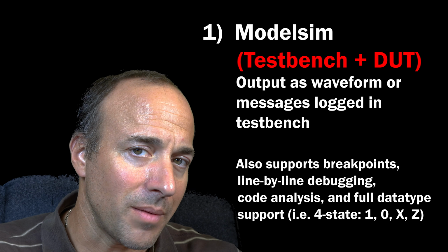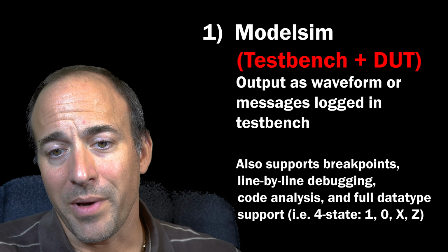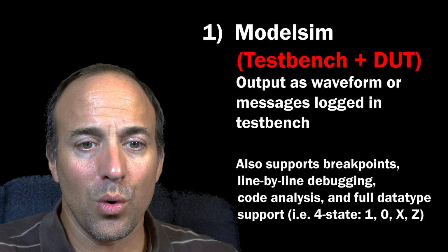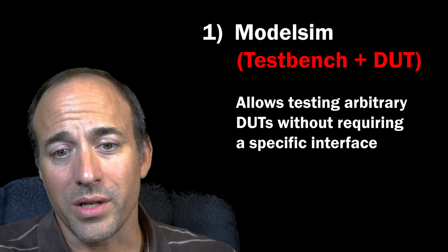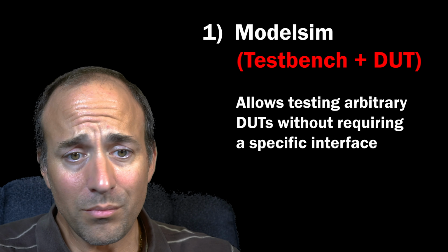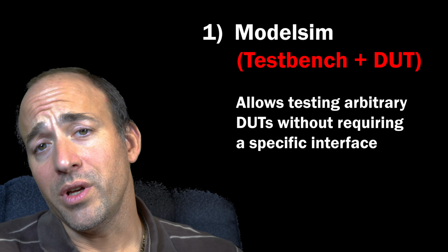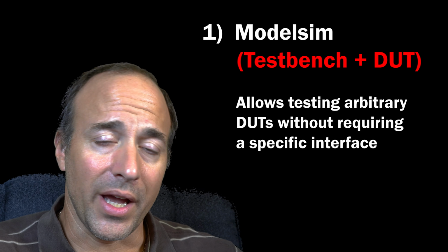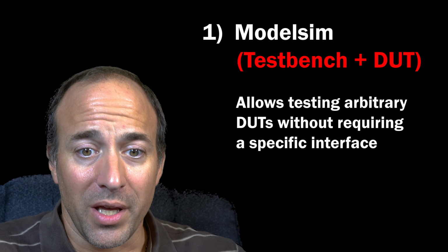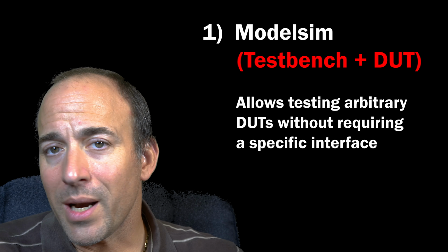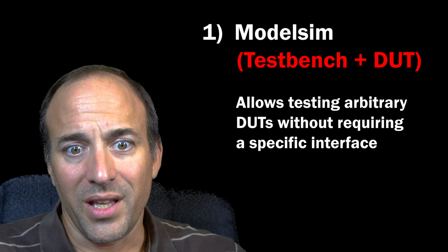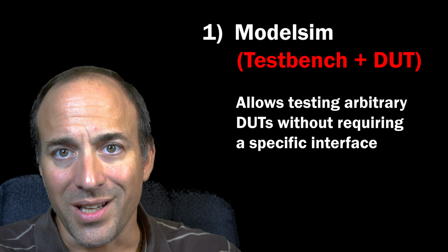The advantage of using ModelSim with your test benches is the freedom to test any individual module that comprises your design at any level of the design hierarchy. For example, when designing your CPU, you can separately test your ALU, your register file, and then eventually your whole CPU as you move from the bottom of the design hierarchy toward the root, and the root is typically the component that you would be shipping to customers.